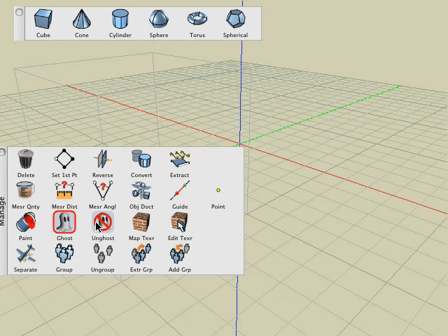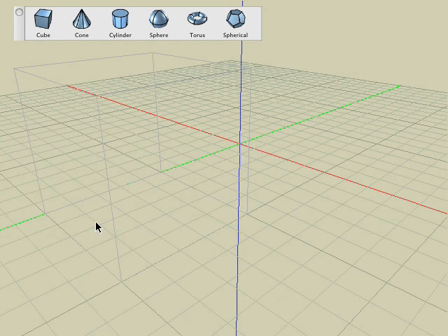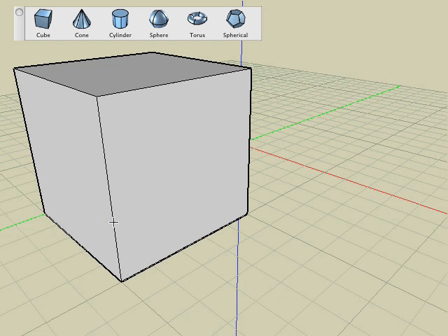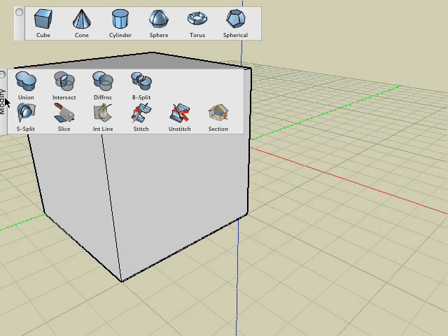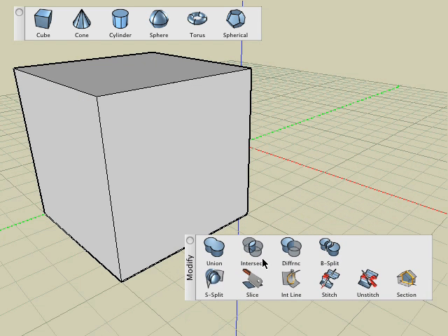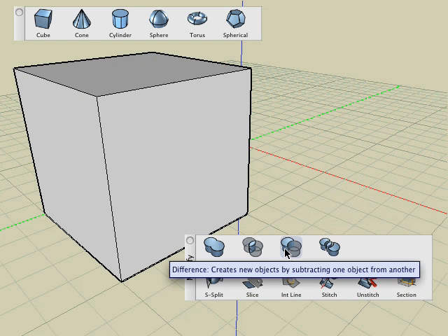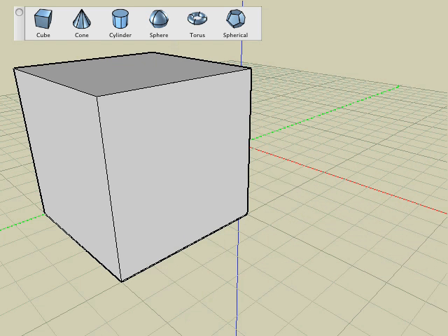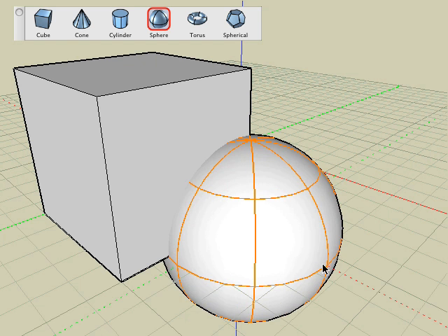As you may have guessed, the Unghost tool is used to retrieve ghosted objects. It's the only tool capable of picking ghosted objects. To unghost, click on the cube with the Unghost tool active. Also, there are certain operations in Bonsai 3D that may result in ghosted objects. One example is the Difference tool found in the Booleans suite. This tool requires 2 intersecting objects and carves the second object picked out of the first one picked.